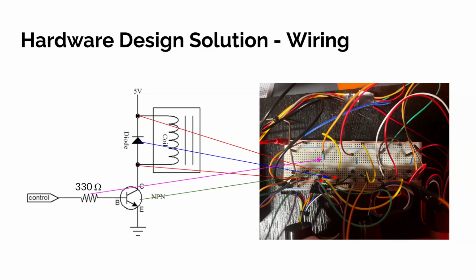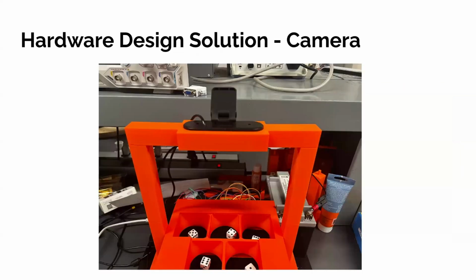The project required the circuit to be repeated for a total of 5 times, 1 to control each of the motors. The final part of the hardware design was the camera stand. Since the program software requires a fixed camera position for operation, it is essential to design a sturdy structure that will allow for consistent camera readings and would not move during gameplay. Our design involves 2 posts, 11 inches tall, with widened feet to ensure stability. A bar spans across both of the posts where the camera rests. The camera slides into an oval-shaped slot above the game board and is secured with no movement.